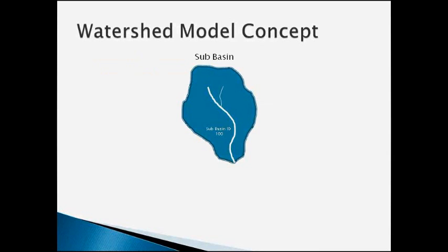A little bit about the watershed model concept. Most watershed models break the watershed up into subbasins. These subbasins represent individual drainage areas or catchments.